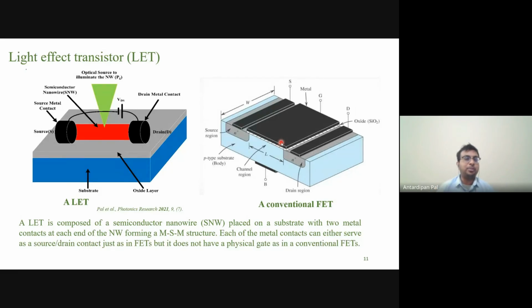However, the problem is that capacitance also leads to some unwanted capacitance, like gate-drain overlap and gate-source overlap. All these capacitances combine to increase the RC delay and energy consumption of the system, right? The delay tau equals RC, and the energy consumption E equals CV squared. As you increase the capacitance, the overall dynamic energy consumption increases.